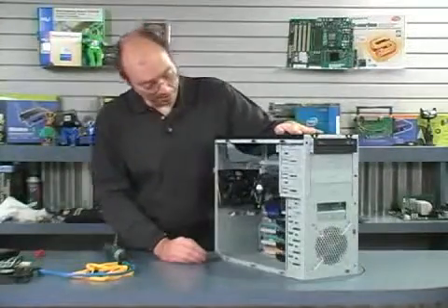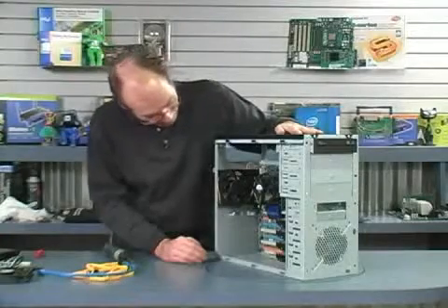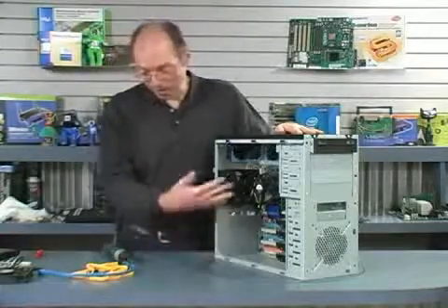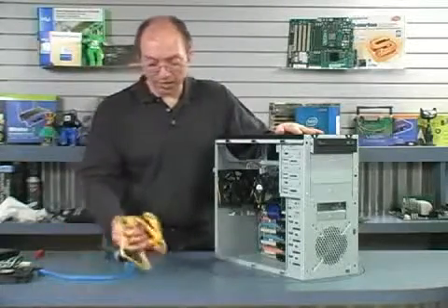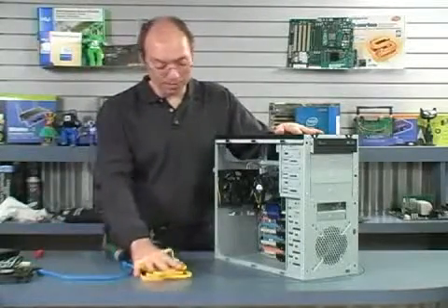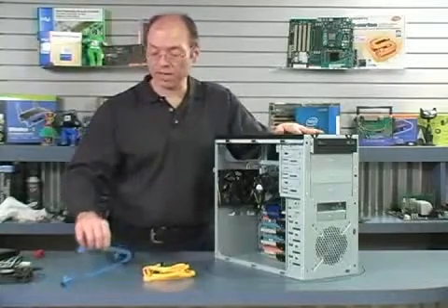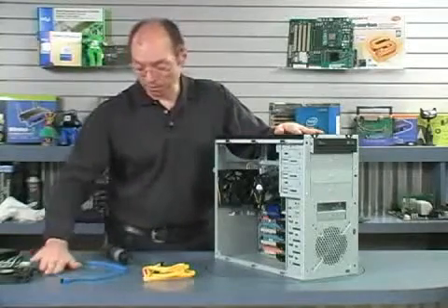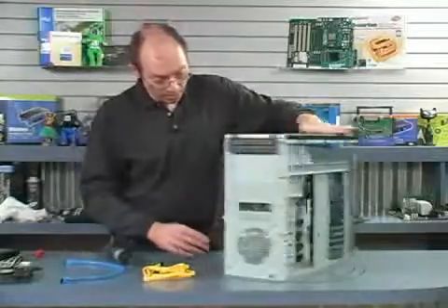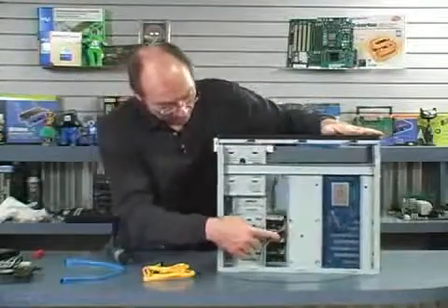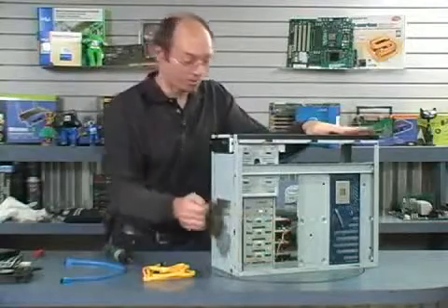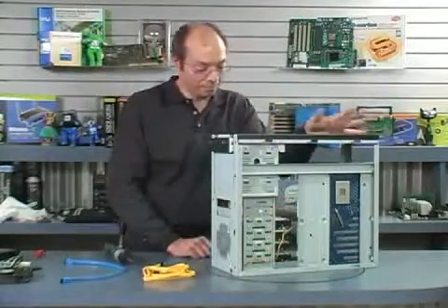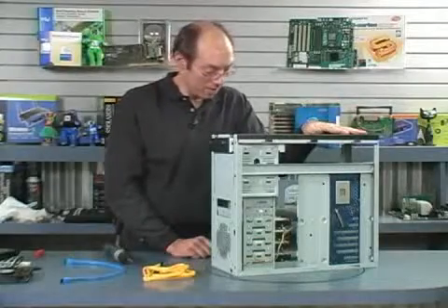Now I need to cable up the drives, and then I can finish installing the power supply. Now, all of these drives are SATA drives, so I've got 4 cables for the hard drives, and I've got 1 extra cable for the optical drive. So they are going to plug in here. Now, this motherboard has these side-mounted SATA ports, which I don't really like. I prefer them to plug in straight from the top. But this is how a lot of them are.